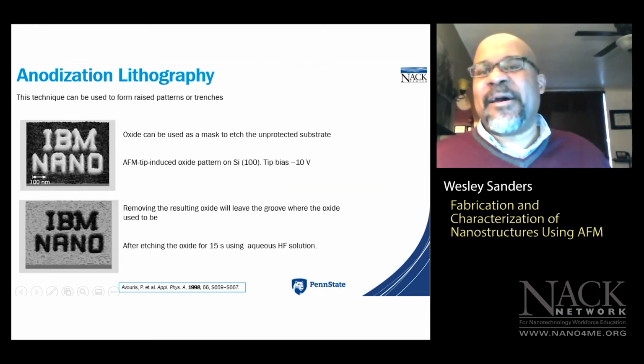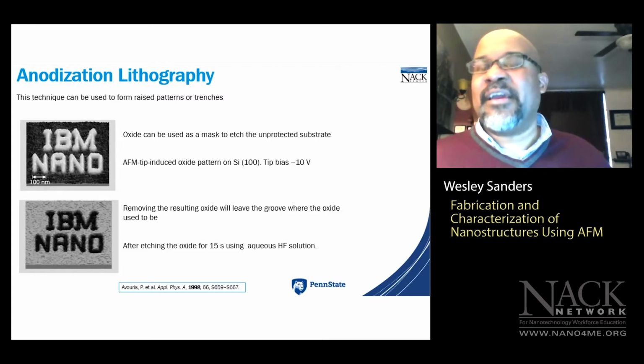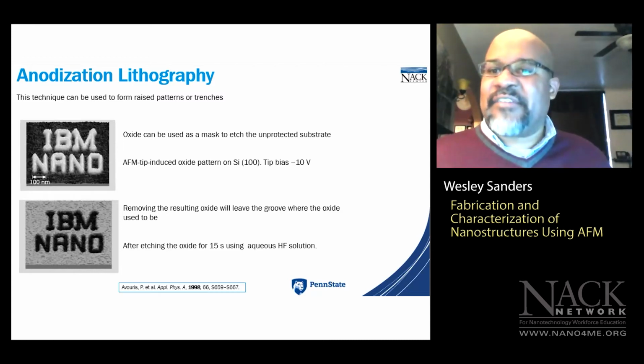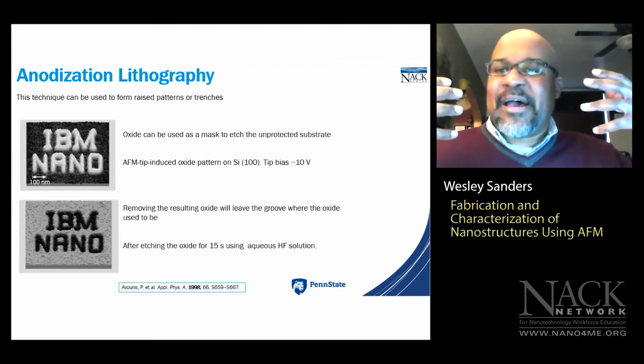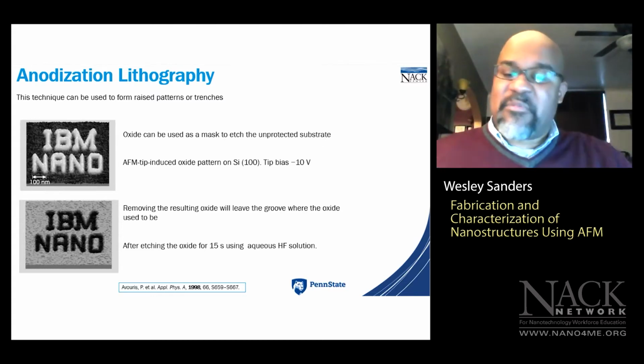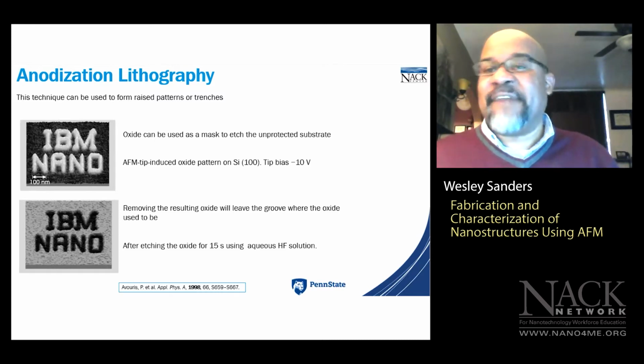Let me talk about an unrelated printing technique, which is photolithography. Okay, so I'm sure everybody in here has heard of photolithography and knows basically how it works. You shine UV light through a mask, and then the mask pattern is reproduced in a photoresist, okay, a photoresist that's coating a silicon wafer.